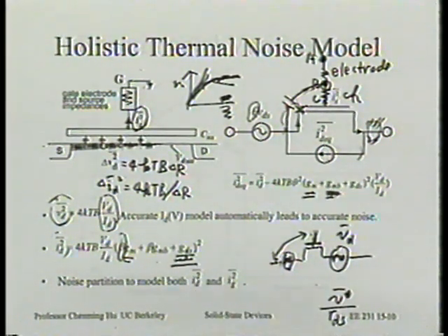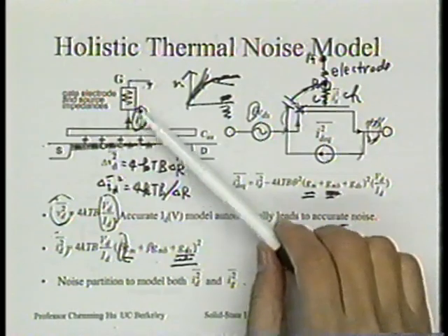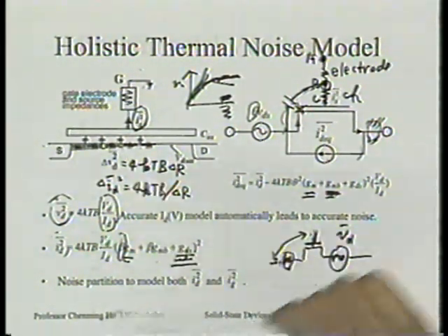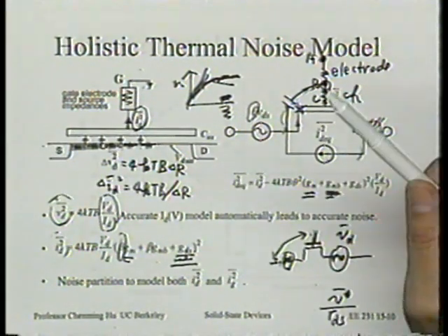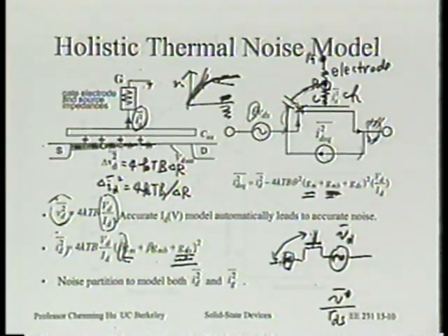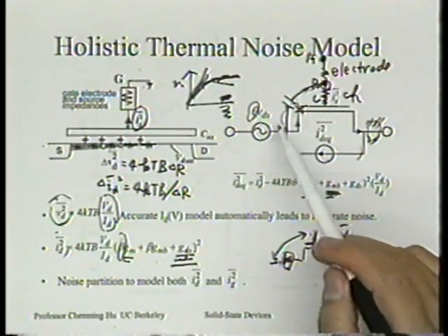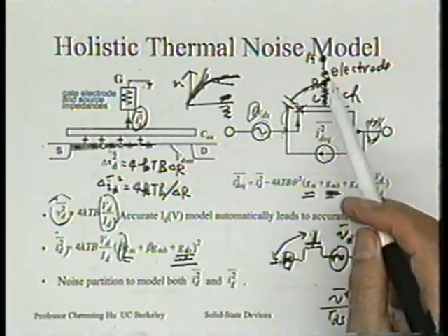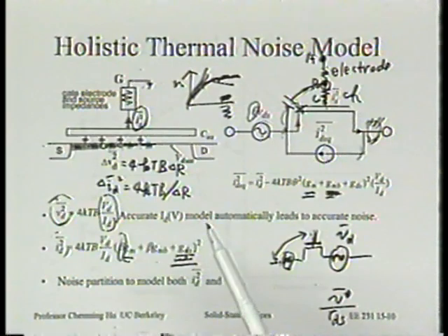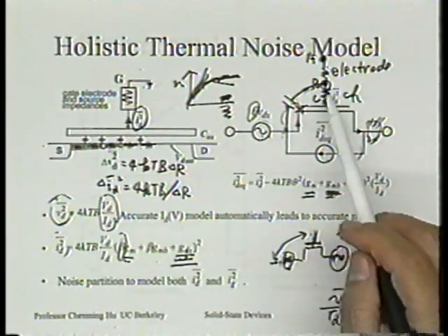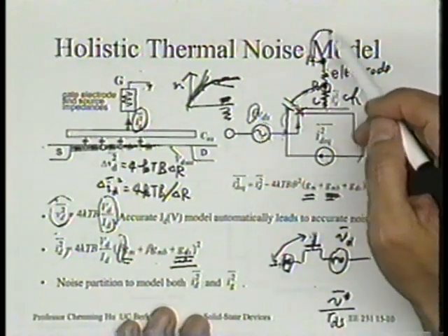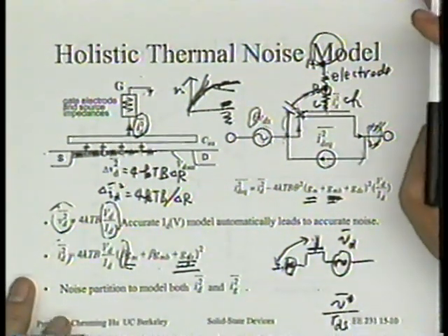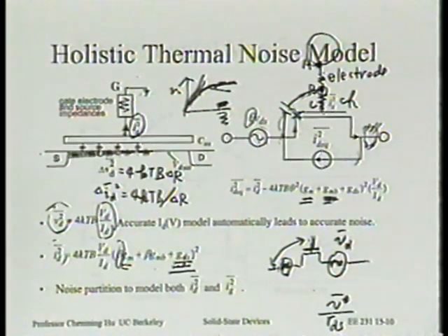So it's very difficult. Most people can agree that the gate-induced noise is coherent with the channel noise because they came from the exact same source, right? But again, if you want to make the problem complicated, then you can start to not know the sign and all that. But if you just follow what I said, the current both come from the same source. One is amplified through the beta only, the other is through this capacitor, then multiplied by the resistor, then through the beta. And in fact, our model didn't even say through that. We even allow you to have any complex impedance in the whole current path. So the signal phase can be whatever it is, right?